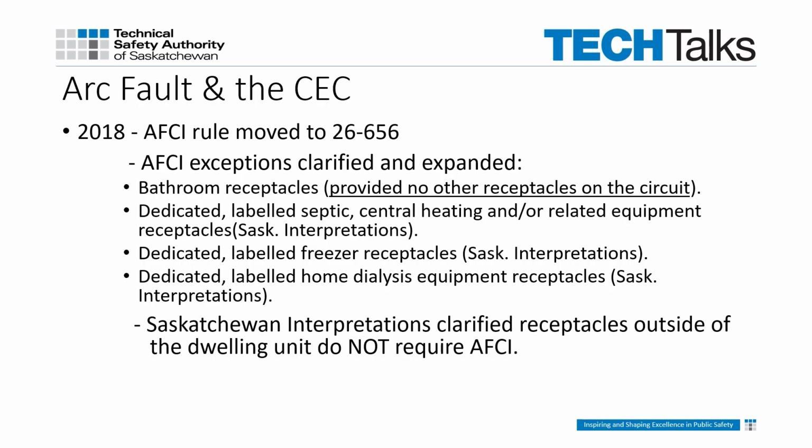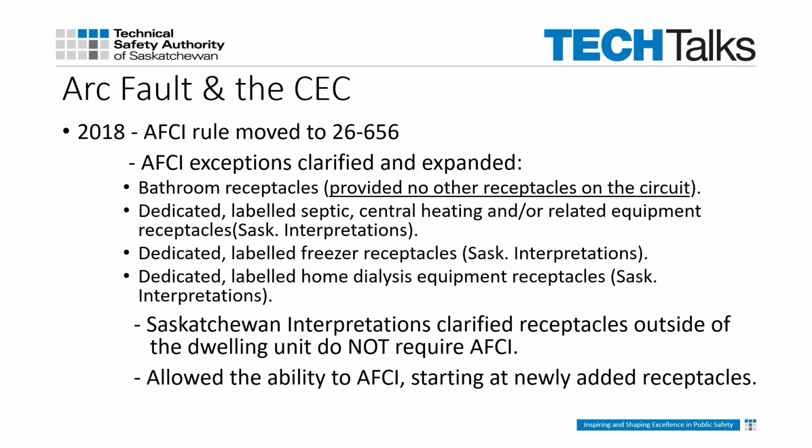As well, the interpretations clearly defined that buildings outside the dwelling unit, such as sheds and detached garages, also did not require arc fault protection. Another change in 2018 was the ability to use arc fault receptacles to protect downstream when adding new receptacles to an existing circuit.